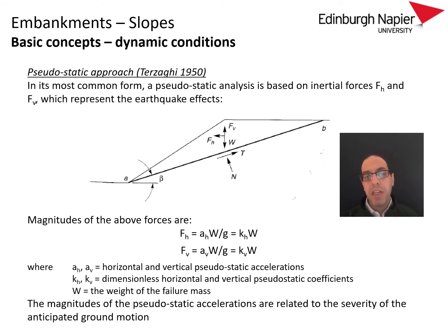The principle here is very simple and very similar to that case of Mononobe-Okabe, because we now have additional pseudostatic forces Fv and Fh, which are proportional to the static accelerations related to the severity of the earthquake, just in the same way that we had two additional static forces in Mononobe-Okabe, and which then become a factor of the horizontal and vertical acceleration coefficients.